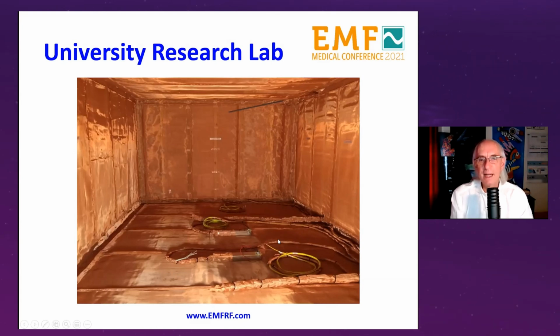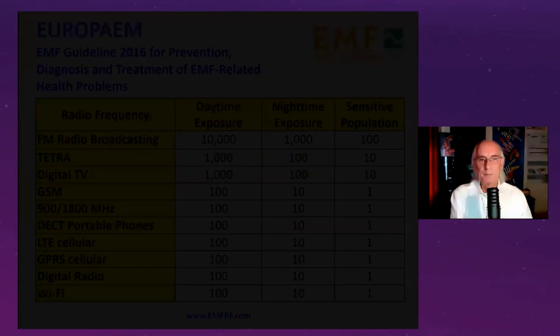So all the data cables and electrical wiring is all shielded as well, to prevent any dirty electricity coming in here or other waves riding on the wires coming into the place. And at the end where we have electrical supplies, we actually have a filter so that any type of dirty electricity is being filtered out inside this particular room.